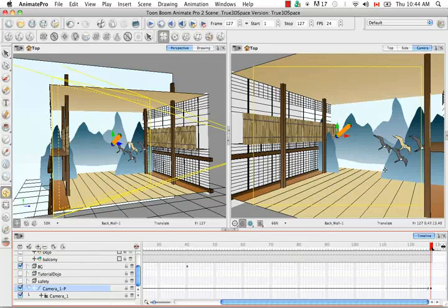So I brought up these background elements because I'm actually going to use them for the next part of this tutorial, which is to show you how to add an ortho lock. A problem that occurs when you do camera rotations for 3D, and you may have guessed this, is that anything that's in 2D looks like a flat piece of paper rotating. So in order to prevent this from happening, we're going to add an ortho lock to the layers in our scene which will be involved in the 3D rotation.